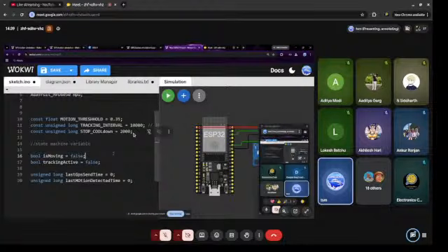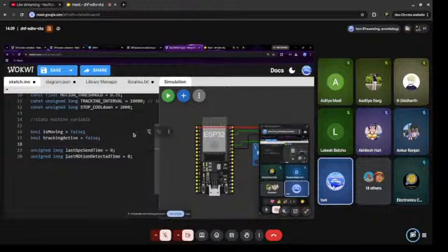After that, these are the timer variables. Unsigned long variables store timestamps. Instead of continuously sending GPS, remember when GPS was last sent, and similarly, when the last motion was detected. These two are initialized to zero currently, and then they keep changing.